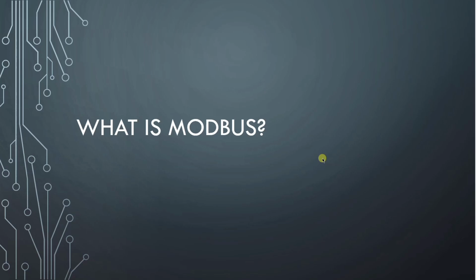What is Modbus? Let's dive into understanding what Modbus is, why we need Modbus, and how to interact with Modbus if it is in your device. Modbus is a protocol usually seen in industrial automation rather than building automation, brought from Modicon to integrate all the devices into a single platform instead of the proprietary protocols which were being used in industrial automation.